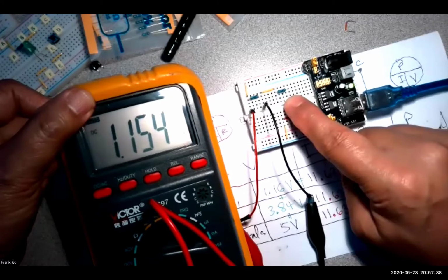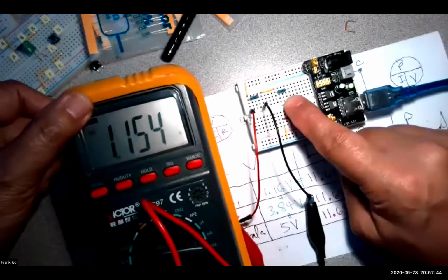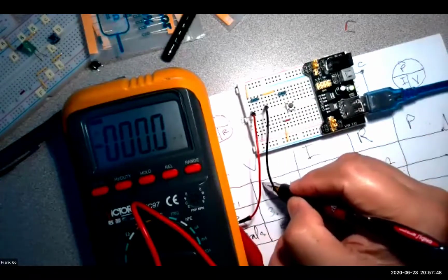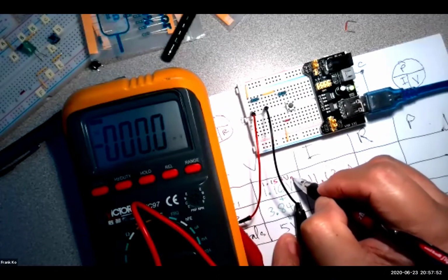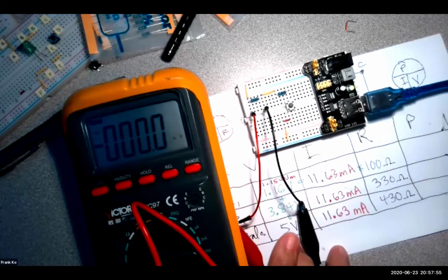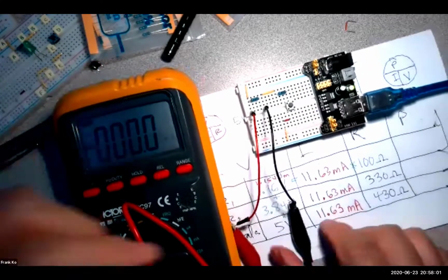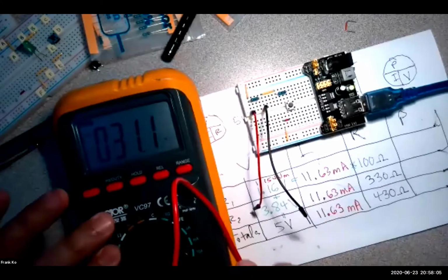And when we go to do a voltmeter measurement, we don't round this one off. We write down all the digits of a voltmeter measurement. So this is 1.154 according to my machine. So I'm going to write this above here, 1.154 volts, M, meaning measured. Does that compare reasonably well with my 1.16 volts? Sure does.